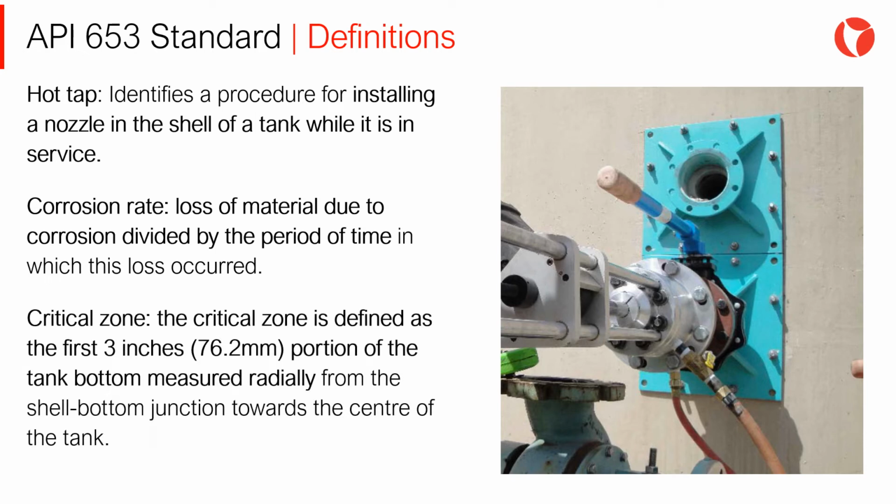Critical zone. The critical zone is defined as the first 3 inches portion of the tank bottom measured radially from the shell to bottom junction towards the center of the tank.